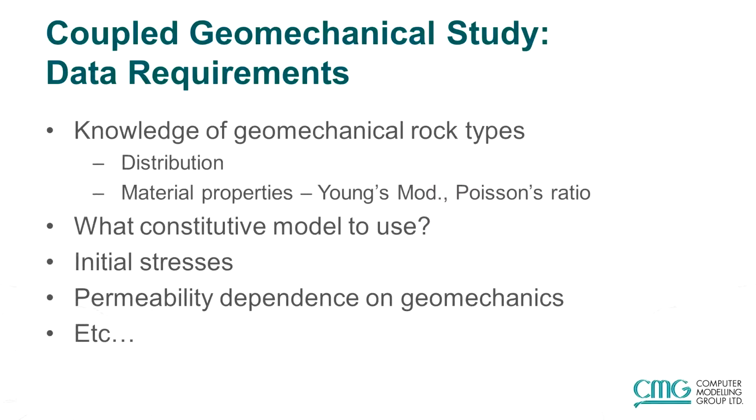Now, before you set up any coupled geomechanical study, you need to ask yourself some questions about the inputs. Do you have knowledge of geomechanical rock types or not? You need to know the distribution of rock types in your reservoir, as well as their individual material properties, like Young's modulus, Poisson's ratio, cohesion, and so on.